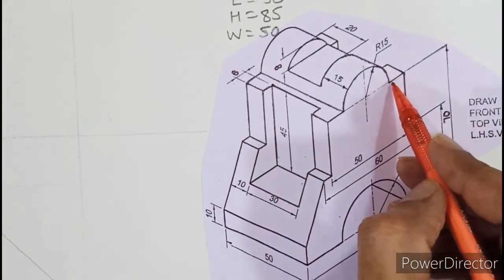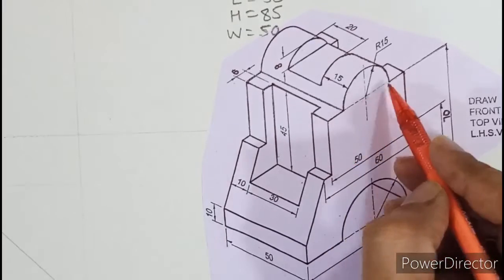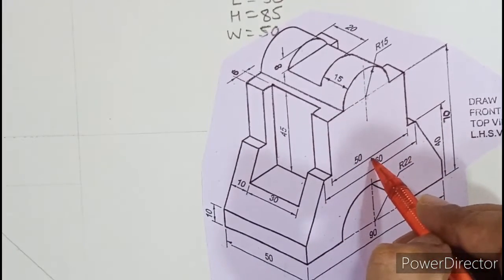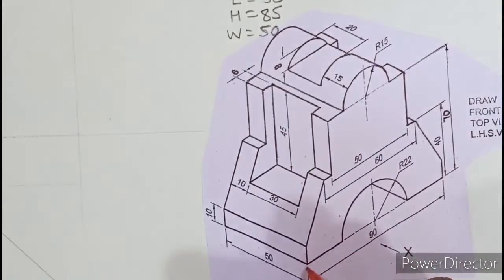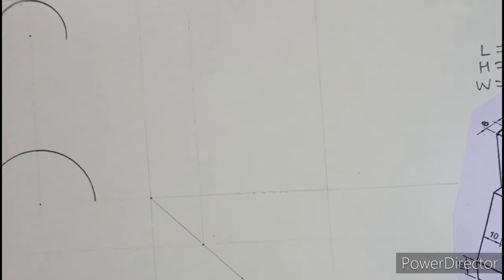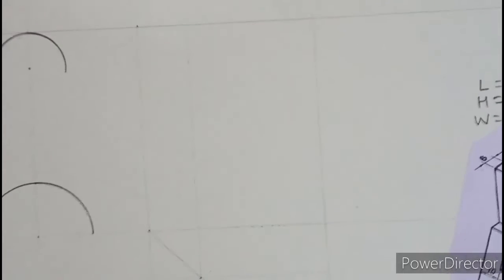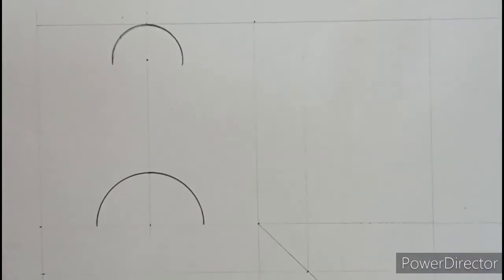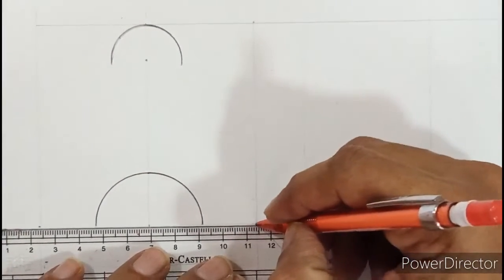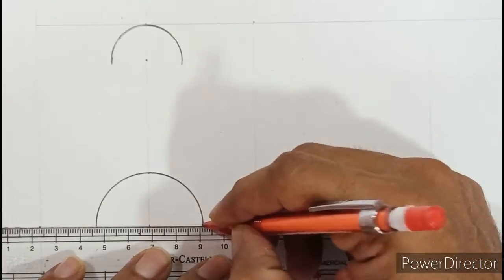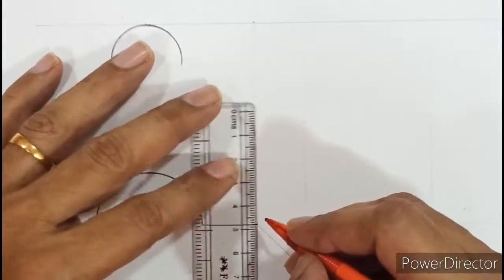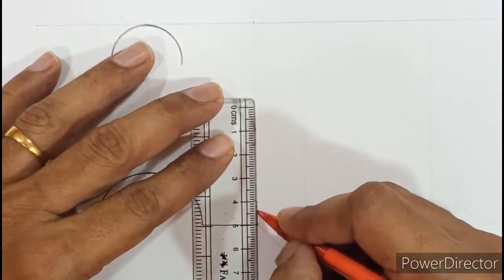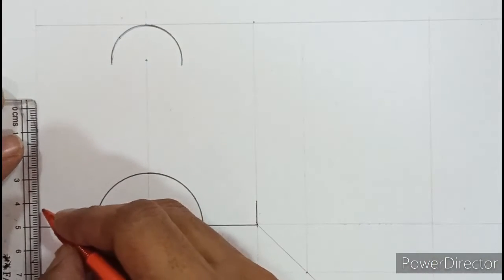So let us first get the shoulders out, by 50. So from the line of symmetry, it is how much? 25 right, 25 left. And we will draw the extensions of 10 millimeter on both the sides. So coming back here, proceeding further, as I told, we need to darken these two edges. It can be seen fully dark, plus we need to raise up by 10 millimeter on either side. So always try to double trace the lines so as to get uniform darkness.